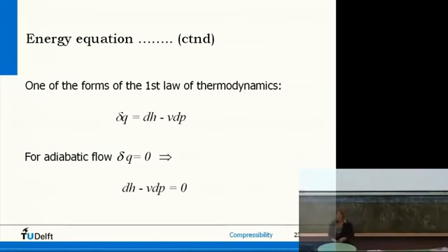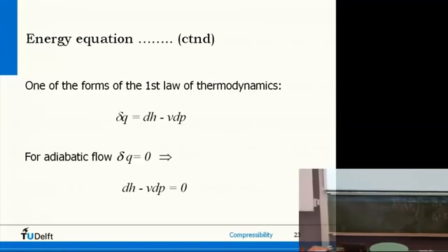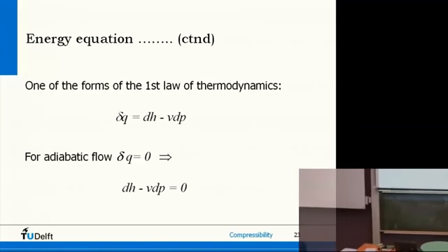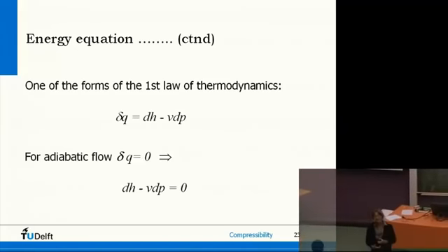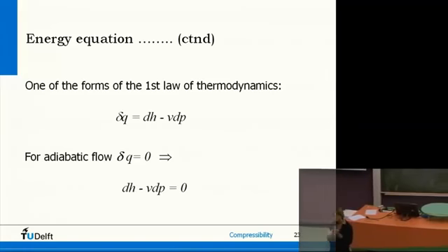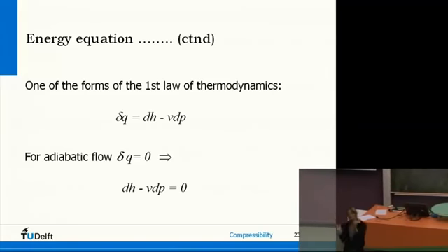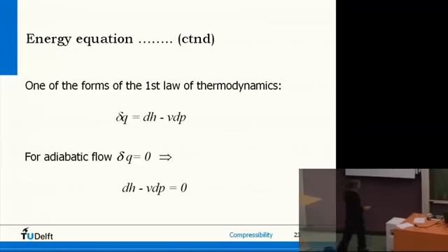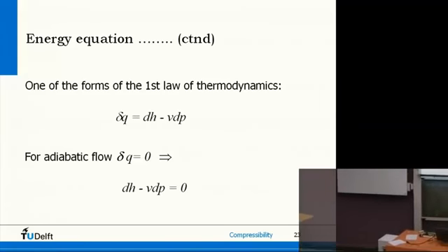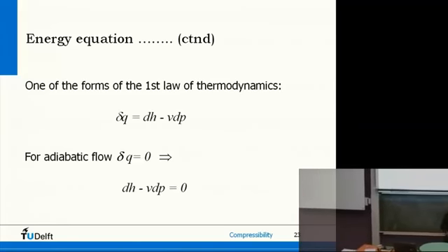So we have here enthalpy and pressures. Now we would like, of course, to get the speeds in there. What relation did we derive, generally valid for compressible flows, which has the speeds in there? No, Bernoulli is only valid for incompressible flows. So what was before the Bernoulli? Where did we derive the Bernoulli from? Euler, our guy Euler. The Euler equation, the differential form: dP is minus rho V dV. So that's relating pressure changes to velocity changes.